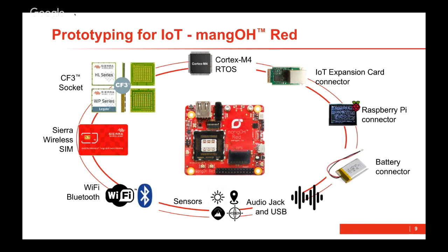So you can make more intelligent decisions like, okay, I'm only going to send this data when I know my battery is above a certain level, or I'm only going to send download data, for example, when I'm actually in a charging state and not in a discharging state. So this allows you to start making more intelligent decisions at the edge side itself.